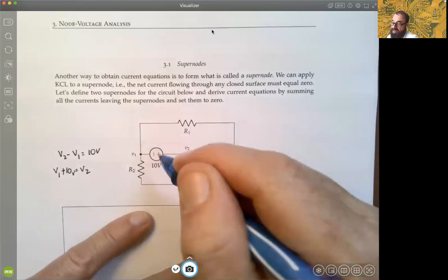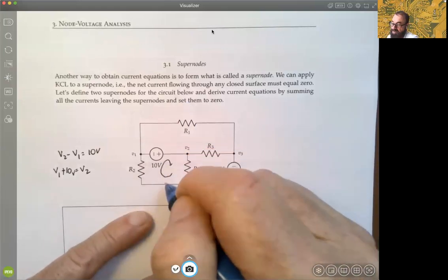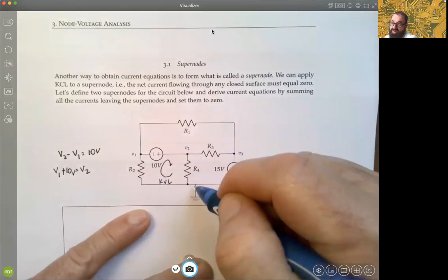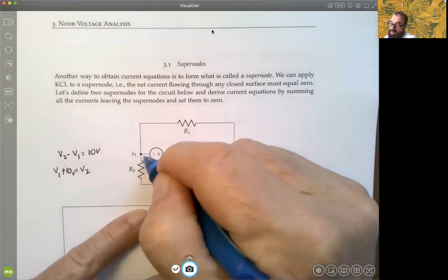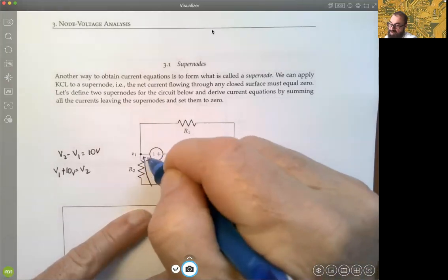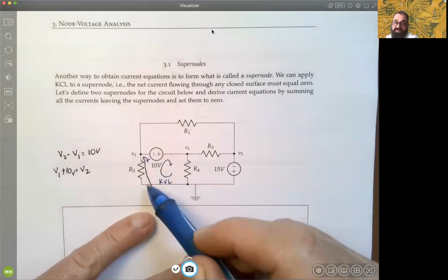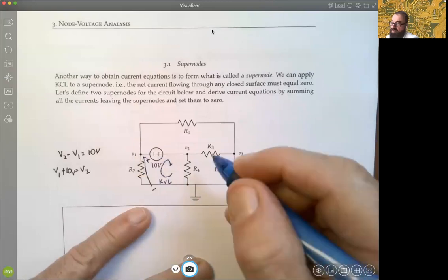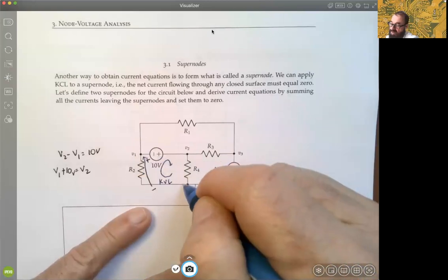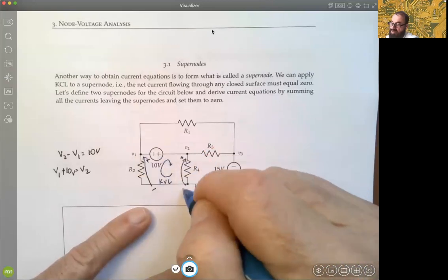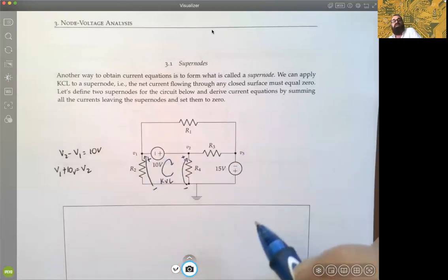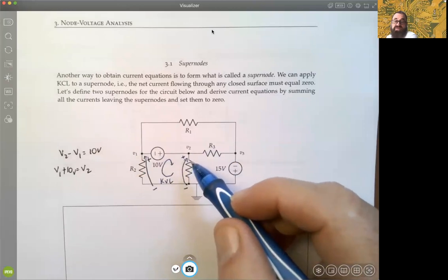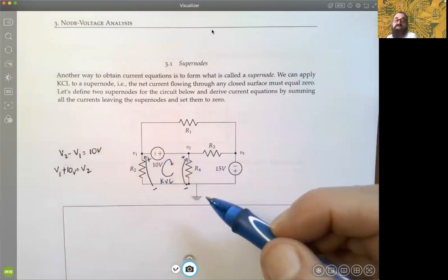If we were to represent a KVL loop here, going clockwise, same thing would happen, because remember, if we represented the polarities for these nodal voltages using our arrows away from negative here at the reference node, but positive at the node, and then same thing for V2, there's another reference arrow, plus, minus. And then as we're traveling, say in a KVL sense, if we hit the head of that arrow, we get a positive voltage. If we're coming up through the tail of it, then we're negative.